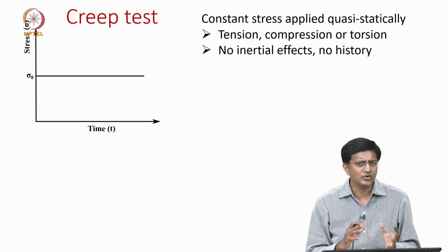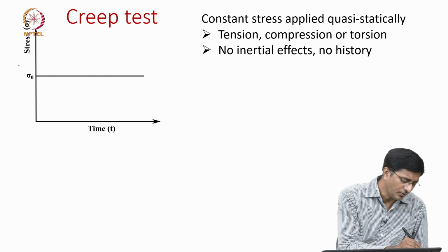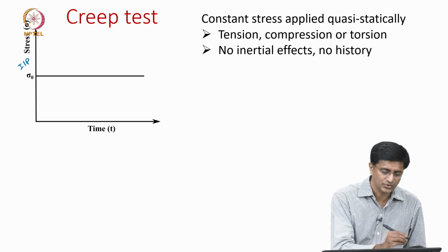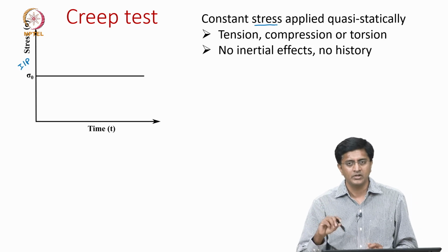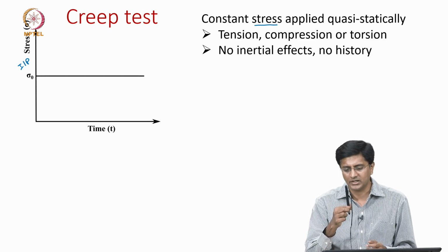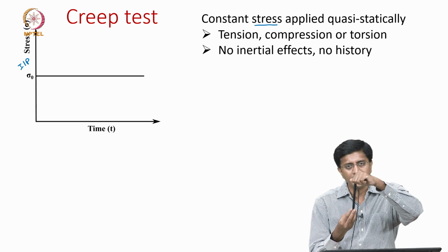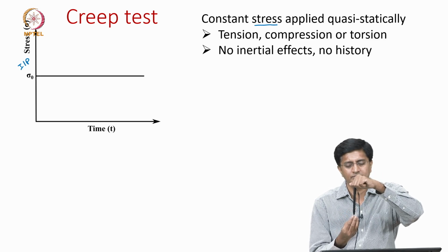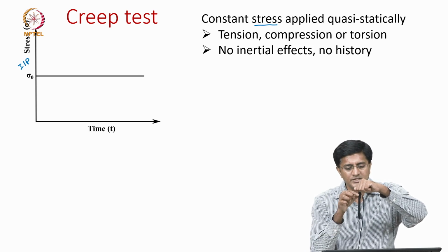So, creep is very close to the relaxation. The only difference here is our input is stress. So, what we are now doing is we are applying a constant stress. Let us think of an experiment like this. Let us say this is the specimen to be tested. I hold it at one end, and at the other end I apply a dead weight. When I apply a dead weight, it means that the load is constant, or the stresses in this specimen are